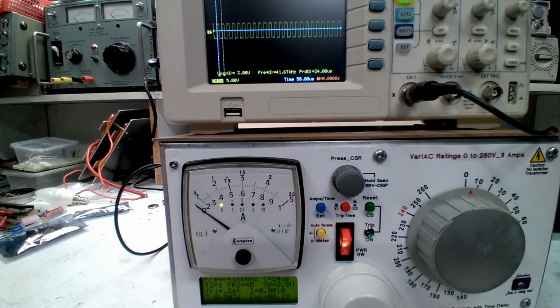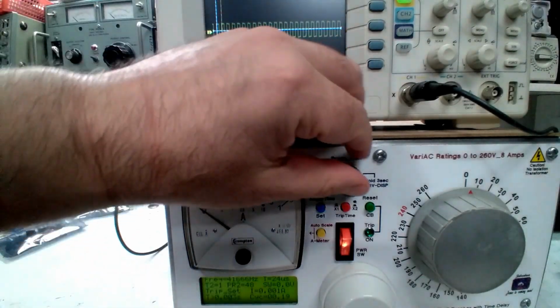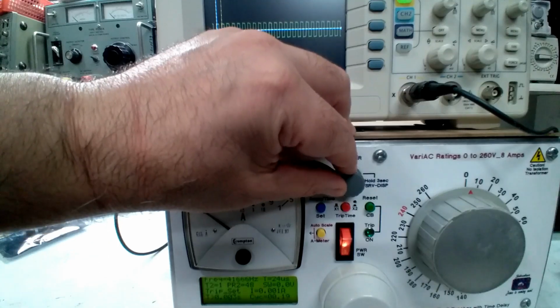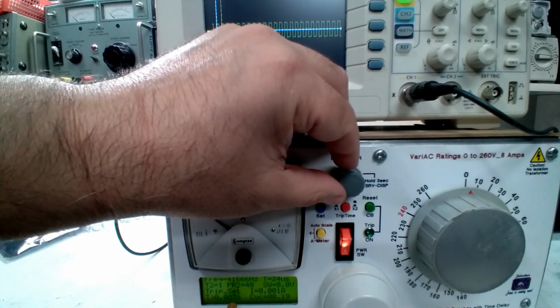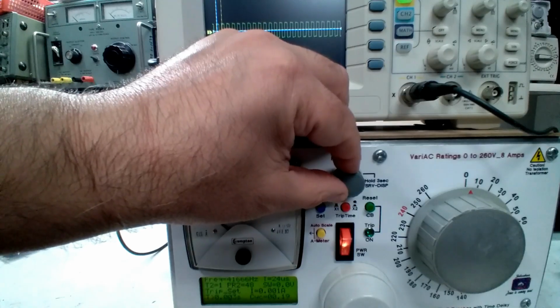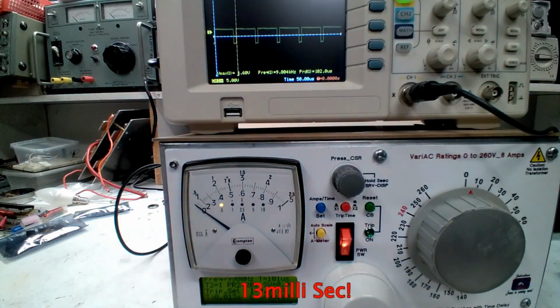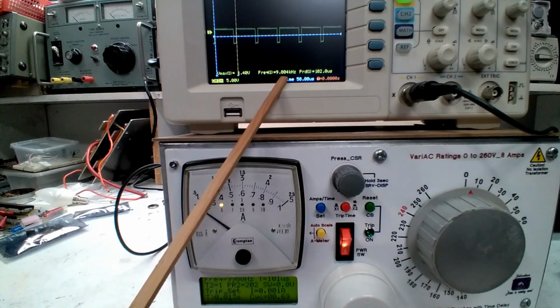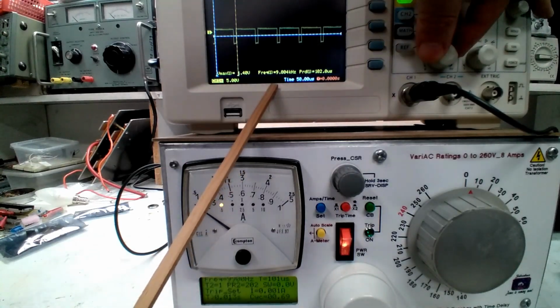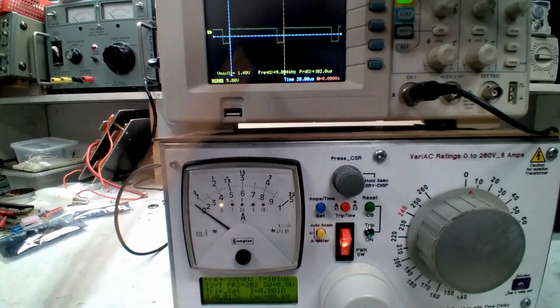So now if I change the frequency by turning the dial here, now I've got 13 milliseconds, and as you can see, my frequency here is saying 9.90 kilohertz or 9900 hertz, and the oscilloscope is reading 9.8 kilohertz. So very close, right?